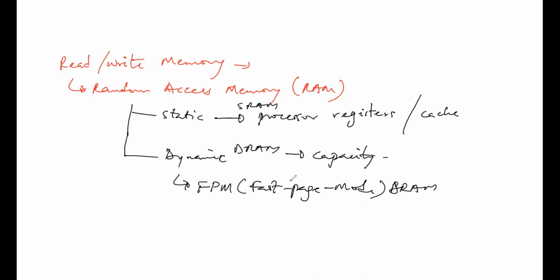Initially, memory is organized as a matrix of bits, like a 32 MB memory could be organized as 8K rows. So we have 8192, since K is the same as 1024, which is 2 to the power of 10. To access a bit, we require the row address and the column address.